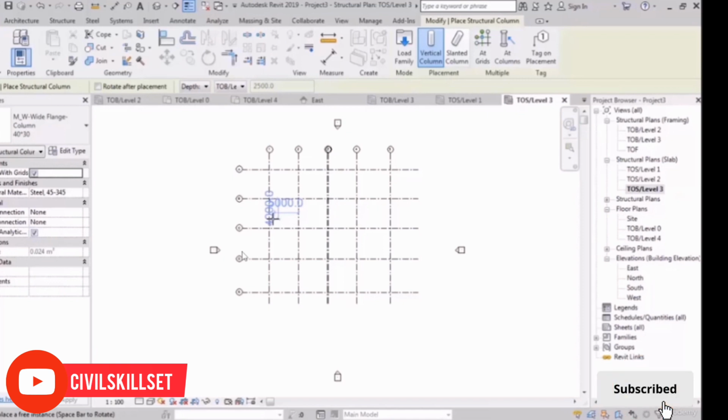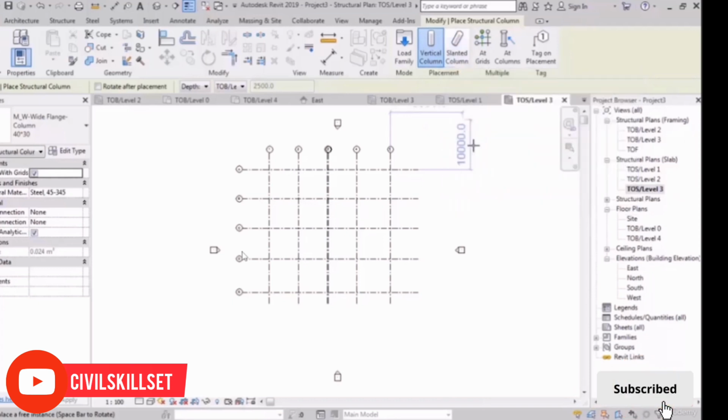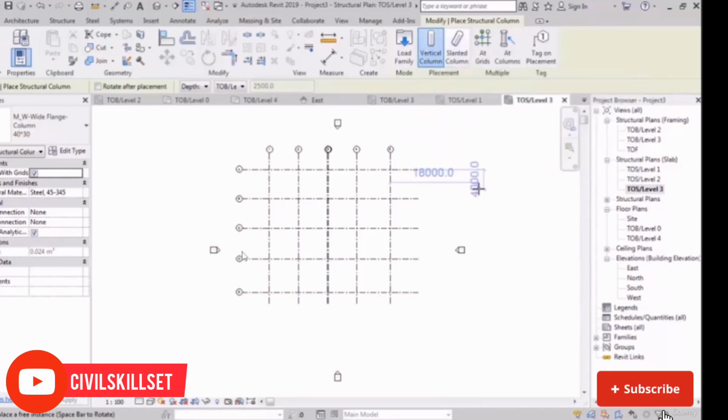Before placing the columns, you have to pay attention to 2 points. The first one: here we have 2 kinds of columns, vertical and slanted, right? Now we want the vertical column, so make sure it is definitely vertical. The second point: the system that places the columns in structure works like this, that the column goes down from the level we are in. Therefore here it should be depth, right?